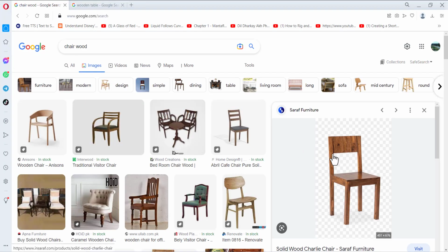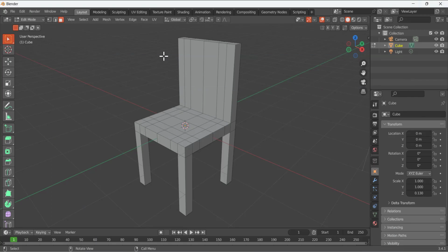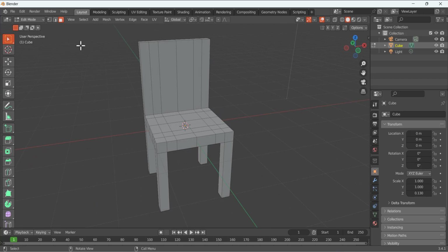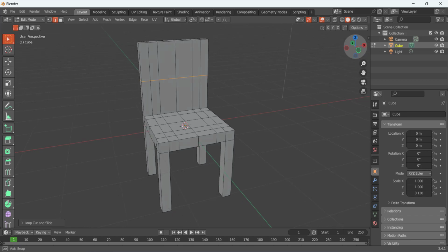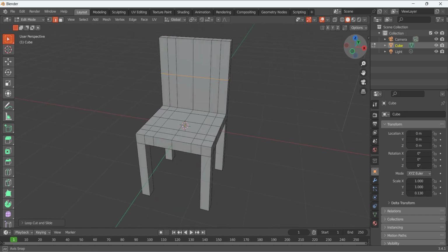Now press the selection and press here, left click to deselect these faces. Next, what we see, you can see we have a cut here and we have something here. Okay, so to make this cut, I am going to add the loop cut. So select the loop cut tool and go here and select it. So you added a loop cut here and you can see when you make this loop cut it is already selected. So press here on this selected box and you can see this loop cut is selected. You can also rotate it and see this whole loop cut is selected.